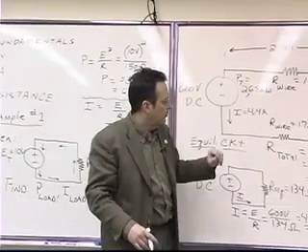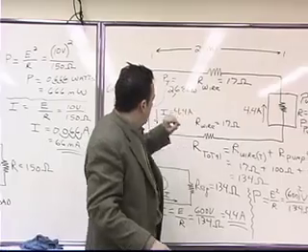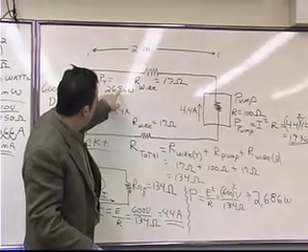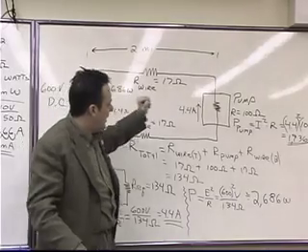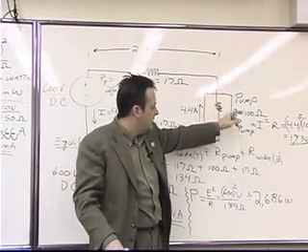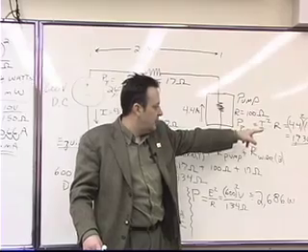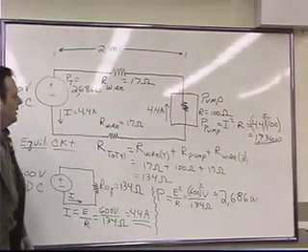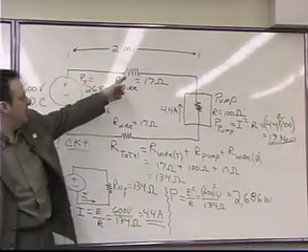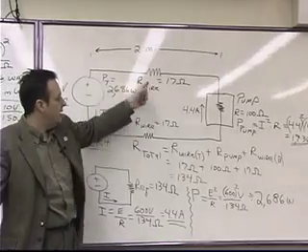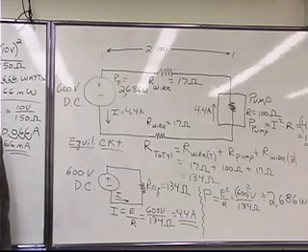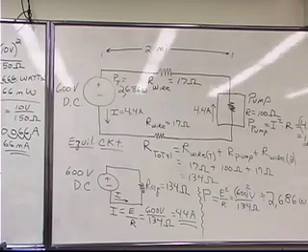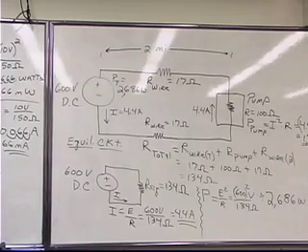Okay? So, if we have 2,686 watts that we're generating, and our water pump is eating up 1,936 watts, then how many watts are being dissipated in our forward and our return wire? 750, or 375 each.